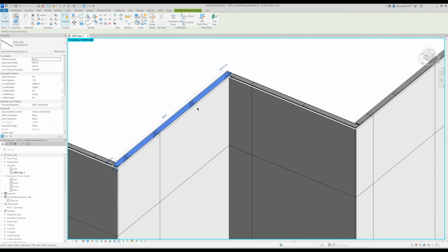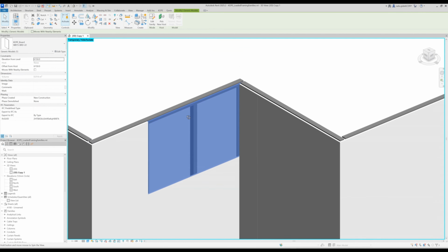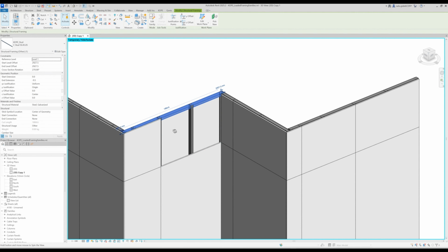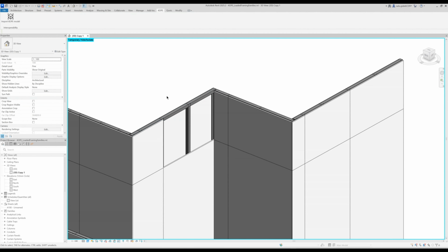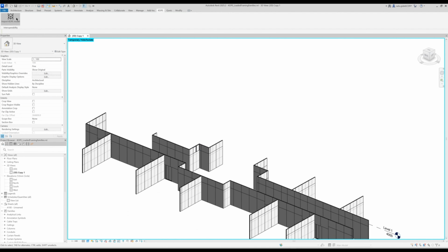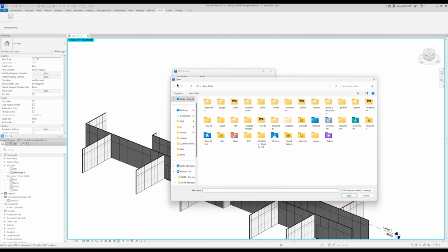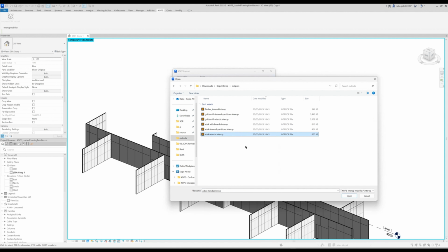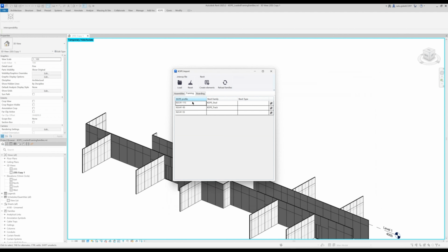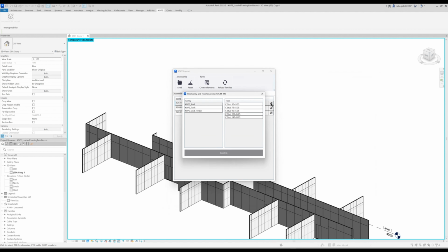We're going to head over and import another floor, essentially. The second floor we're going to be importing is one with Extenda telescopic framing. So we're going to fire up the import UI again and select the interop file. The thing you'll see about this telescopic framing is there's a lot of members, but there's no mapping. So this is a case where you have to do the mapping yourself.